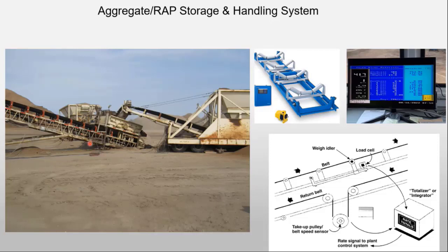You can't really see it very well, but on this particular conveyor there's what they call a weigh bridge. This weigh bridge looks like the one up here at the top where I have the pointer, and it will weigh at an instantaneous value what's going over on the belt. There's another mechanism that times it for a certain time, and then there's a totalizer at the bottom that totalizes it all up. So you get a rate, for instance, tons per hour. That's an important term in asphalt, a rate, because everything has to be geared to certain tons.